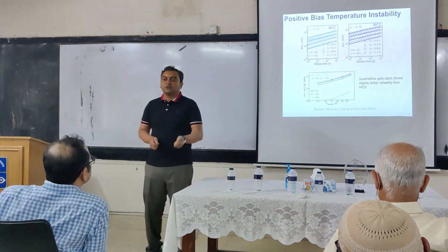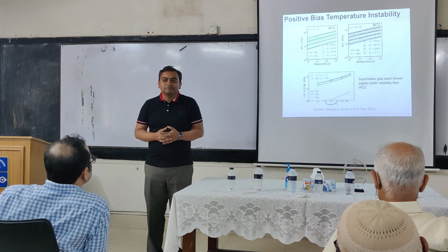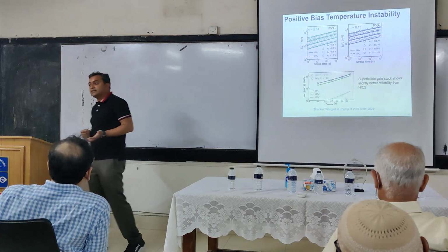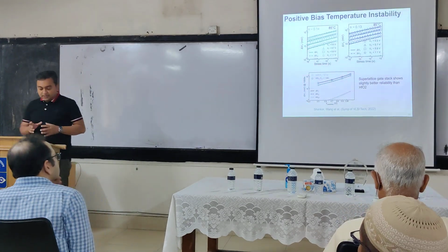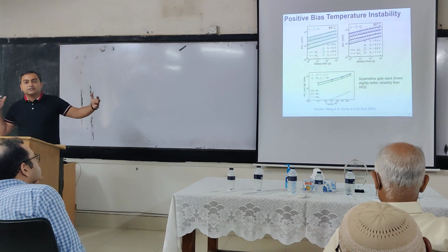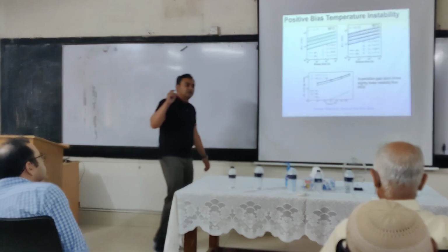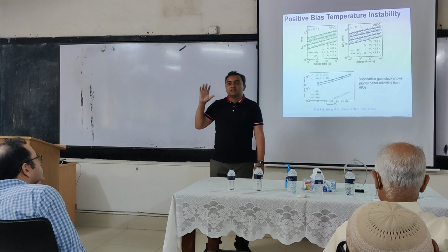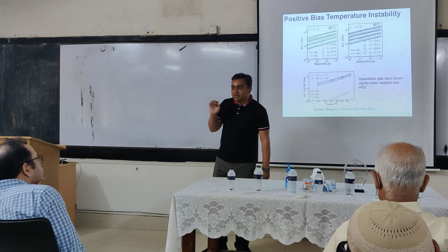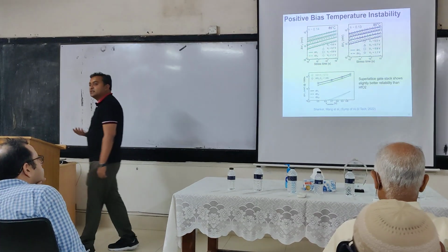I cannot just give you a good device and say, okay, go use it, but the device stops working after half an hour of use. Then you will get very angry, right? So as a result, what people do is they try to measure the reliability of transistors, and the reliability depends heavily on the grade of silicon. So when the industry went from silicon dioxide to hafnium dioxide, this was the biggest question: will the reliability be satisfied with a new gate oxide?